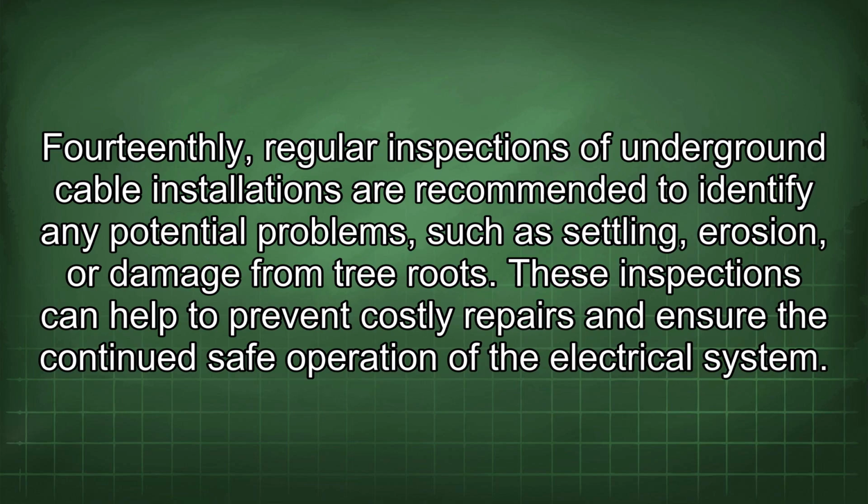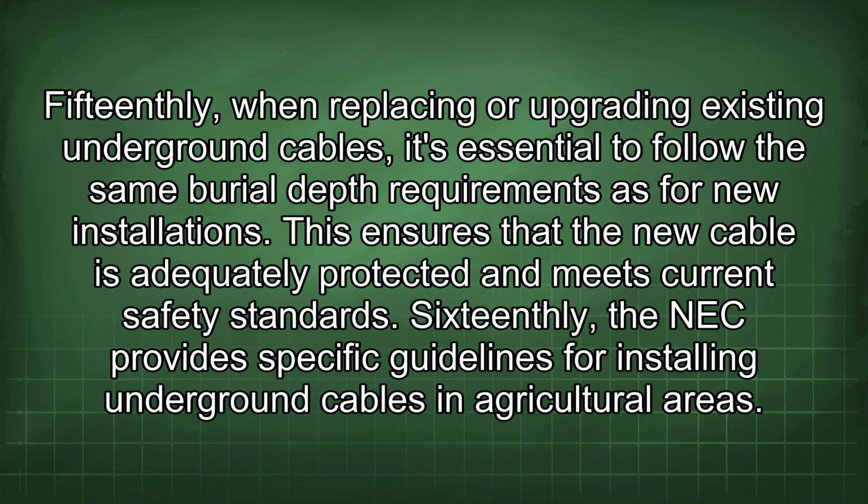14thly, regular inspections of underground cable installations are recommended to identify any potential problems such as settling, erosion, or damage from tree roots. These inspections can help to prevent costly repairs and ensure the continued safe operation of the electrical system. 15thly, when replacing or upgrading existing underground cables, it's essential to follow the same burial depth requirements as for new installations. This ensures that the new cable is adequately protected and meets current safety standards.